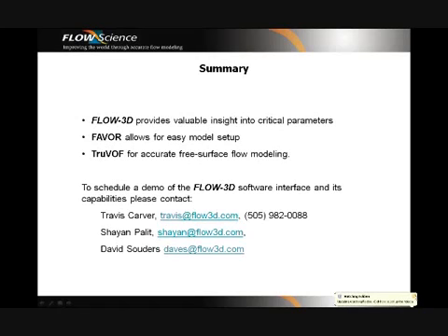One question is, for a submerged horizontal jet, do you use a one-phase model or two-phase models? Depending on those questions, there is a phase for the fluid and the sediment itself. The sediment is a scalar quantity stored in computational cells, and it defines the property of the sand or whatever material you're eroding. And it's affected depending on a number of properties like density and shear parameters and so on.